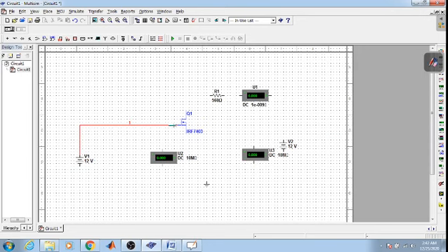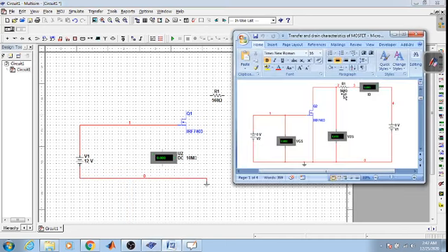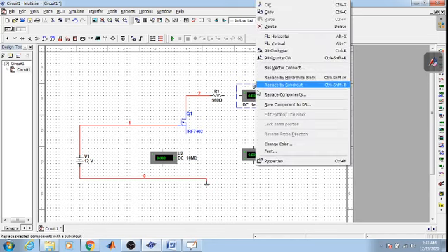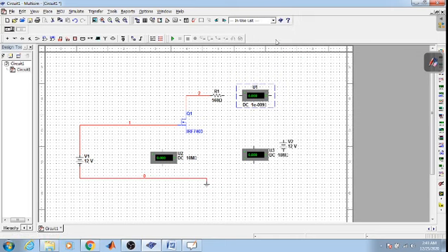So the voltage is given to the gate terminal. The negative is connected to the ground. Then we are connecting a resistor to the drain. So this is your drain. Then that has to be connected. Here this is positive and negative. Here it is positive, so you just flip horizontal so that the positive terminal of the ammeter is connected to the positive terminal of the battery.